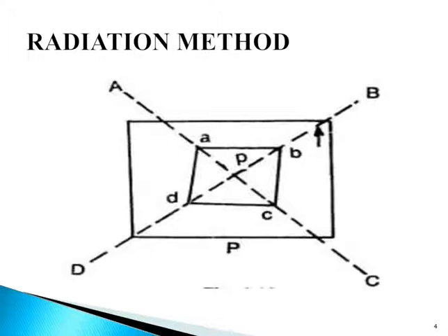Next, point P is bisected on the sheet to represent station point P. So to represent this point, we have to bisect the point. This way the point P on the ground is marked on the sheet here. Next, the north line is marked on the right hand top corner of the sheet, we can see it here in the arrow, with the help of a true compass or circular box compass.